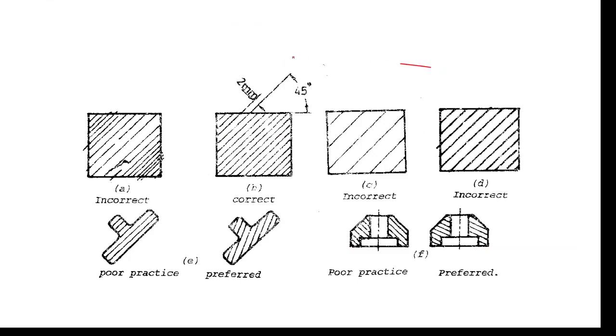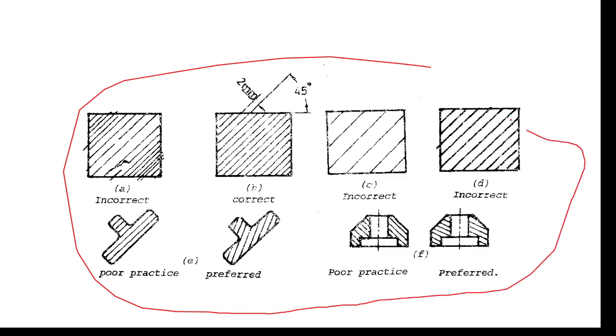This slide is about some mistakes. Those are in question in hand drafting, of course. Well, this is a wrong hatching. Why? Because the spaces between the hatching lines are not equal to each other, and although the surface has ended over here, you see the hatching lines have been further extended.